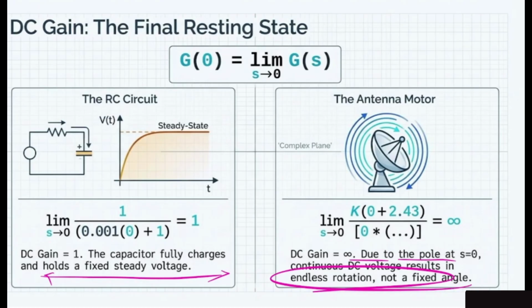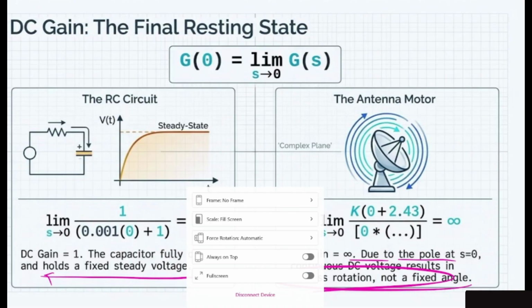If you guys remember, we talked about the DC gain. DC gain, just like the normal part that we had, is about the DC value of your electrical circuit. For example, you have the voltage source, it has the DC value or DC offset, and you have the AC value. So DC gain means that, as I mentioned, at the very beginning of condition, the DC gain is going to give you the response of the system while your input is going to be something constant. It means that it doesn't have any frequency.